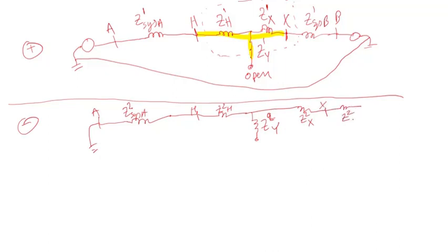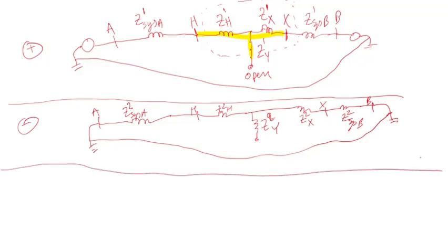And Z2 system B. So you have the B system. So basically, they're the same. It's just, and these are connected basically to ground. Both systems are grounded. So the only difference is the positive sequence, you have the sources. The negative sequence, you do not have this source. So that's the negative sequence impedance.